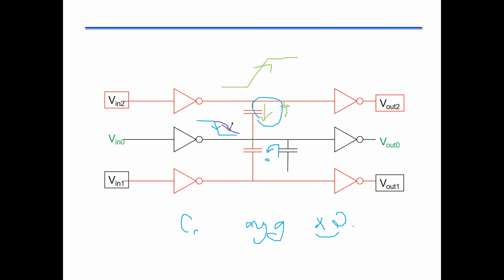Okay. So you understood that if this is going up, it's throwing a charge on its own capacitance, and it's also throwing charge through the coupling capacitor. It's like a partial connector. Anytime I have a slope, a current will flow through it. So logically speaking, if I'm trying to discharge things through this inverter here, but this inverter has its PMOS on and is trying to charge things up, it will throw a current.